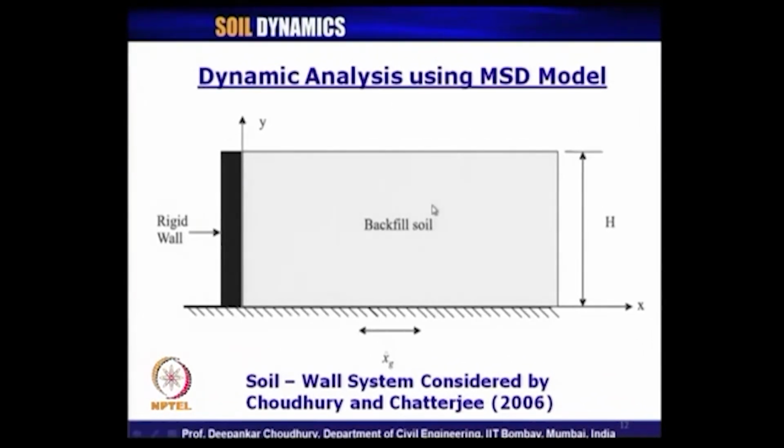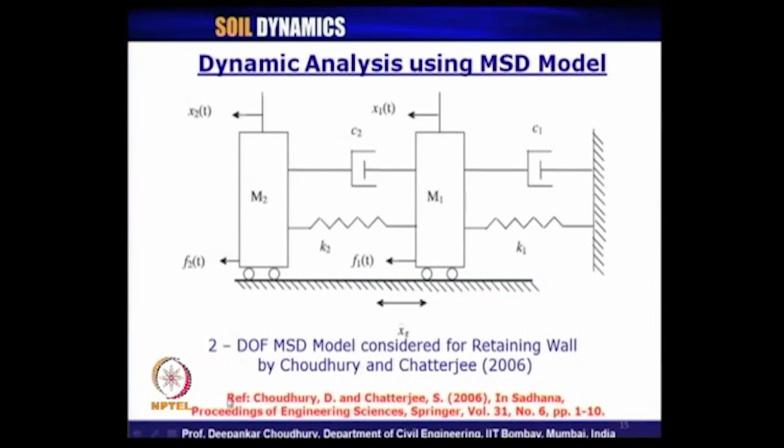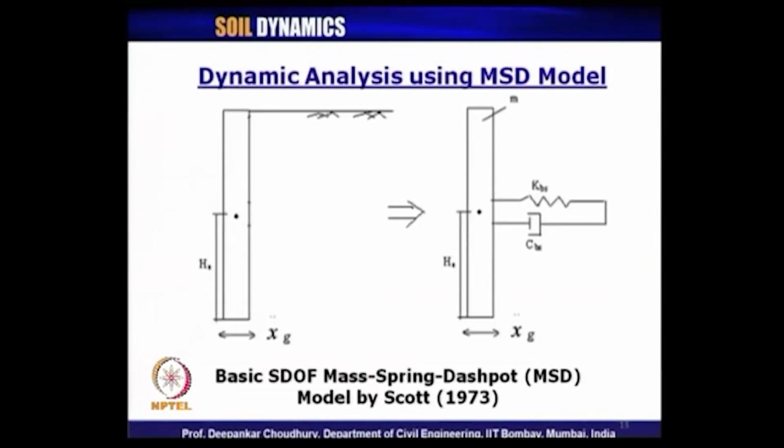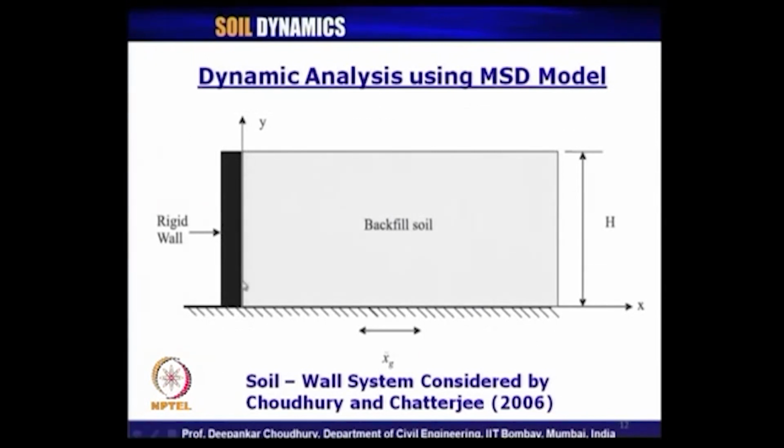Clear? So, if you go through this paper, which I have already given the reference, you will get all the details, and that way finally, we have found out for different conditions of course, applied dynamic forces, what are the different zones of influence. And from that, now we are ready to calculate M1 very easily, because it is a simple rectangular area we have considered in this figure in our basic model. Height is known, this influence zone is also now known, and other dimension is per meter always we consider for retaining wall plane strain problem.